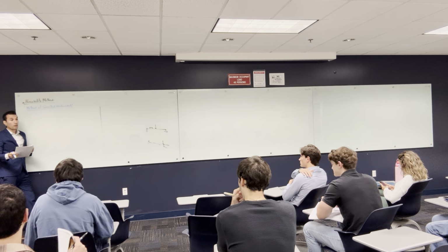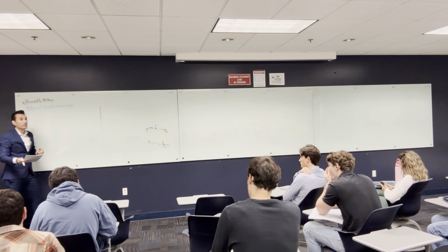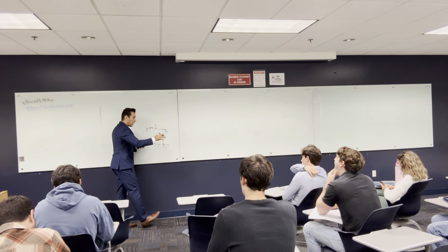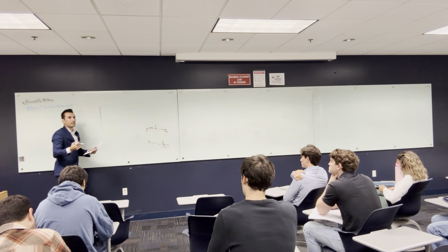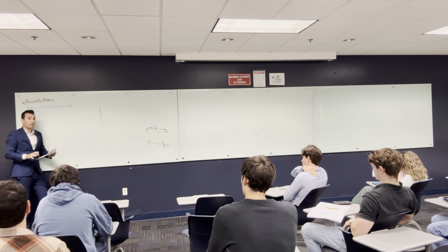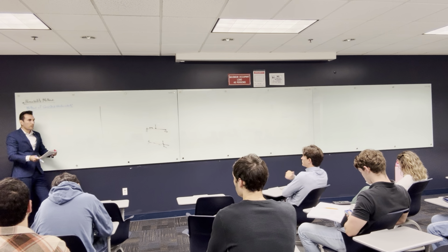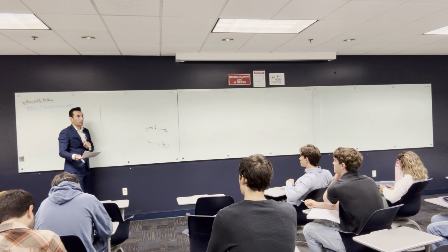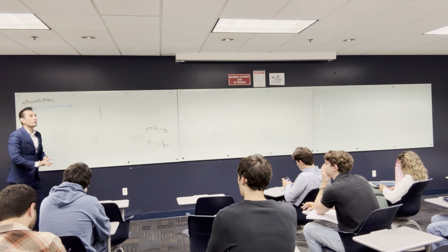The first thing is called compatibility. The compatibility is that the deflected shape is consistent with the boundary conditions or the constraints that you have here. And the second thing is that this method has to satisfy the stability or the equilibrium of the structure. We are going to see how this method works, how we use all this to make the structure compatible and in equilibrium. But before I start this method, I want to get you back to the redundance.